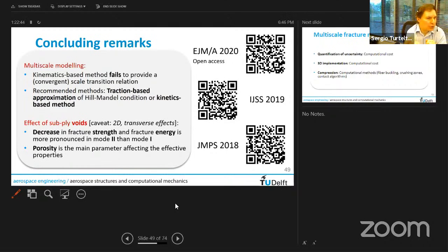You did mention mesoscale. In these computations, we don't have a mesoscale. We just have a small one and a large one. So micro and macro. And the way we do the average is that we take a micro scale volume element, load it until it breaks completely. And then we do the post-processing, where we identify the location of the crack.